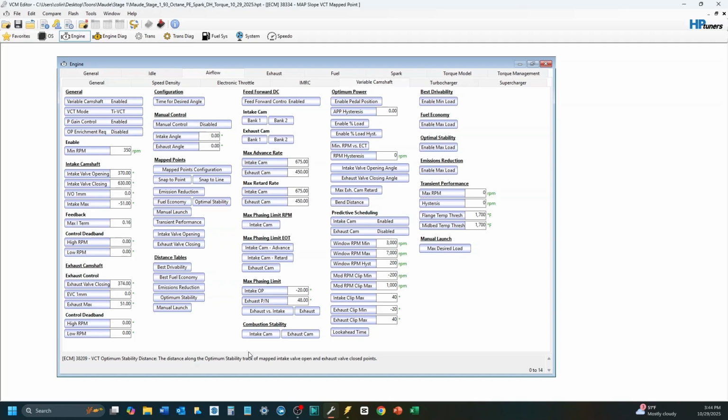Now, is this time consuming? You bet your ass it's time consuming. There is a lot of logging. Each run of a speed density log should take 45 minutes, and it's usually 2 iterations. If I have 26 tables and I go through 2 iterations, I do a 1.0 to start, then file 1.1 and 1.2, that's 3 logs for 26 tables. That means we're going to log 75 times, roughly.